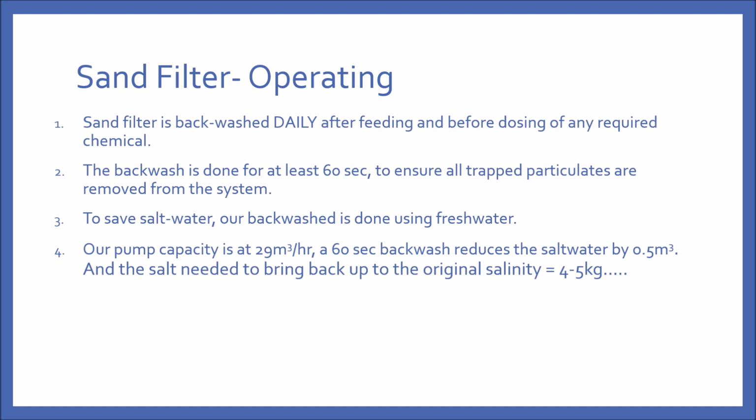Suspended solids that are trapped inside the sand filter have to be removed from the system, and the removal method is to execute what we call backwashing. On a daily basis, we have to backwash at least once to ensure that the trapped particulates do not start decomposing in the system and further deteriorating your water supply.